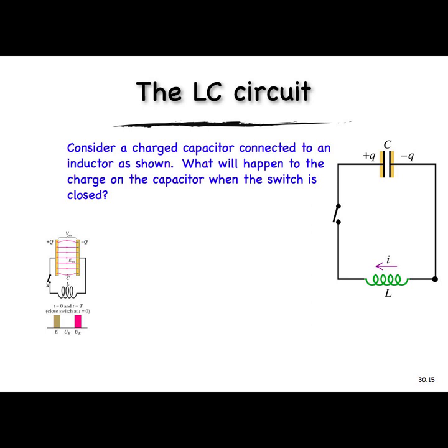But because this change in current is so quick, for a very short instant in time, and you can see that on the oscilloscope, it's only a very short spike, but I get this big peak. You've probably seen this effect yourself if you've ever unplugged a refrigerator or anything with an electric motor, an air conditioner. You ever unplug it and see a spark? Okay, that's what you're seeing. It's unplugging it just like that.